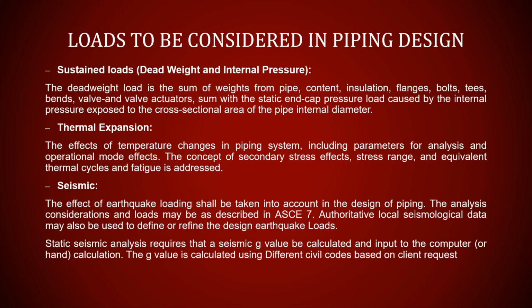The thermal expansion, the effect of temperature changes in the piping system, including the parameters for analysis and operational mode effect. This is why we need the operational modes. The concept of secondary stress effect, stress range, and equivalent thermal cycles and fatigue is addressed.